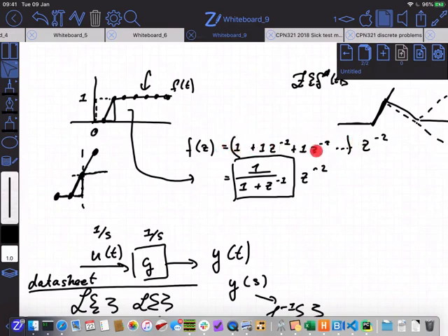So if I have this long form polynomial in Z, super easy, right? Write it out, look at the coefficients with your eyes, write them down one by one, and notice the power of Z to understand which exact sampling period it is associated with. So here the power is 0, and so the time is 0, right? Here the power is -1, so it's the first sampling time, and if it's a 2-second sampling time, that is time 2, okay? As long as you keep those things straight, reading one of these is really straightforward.